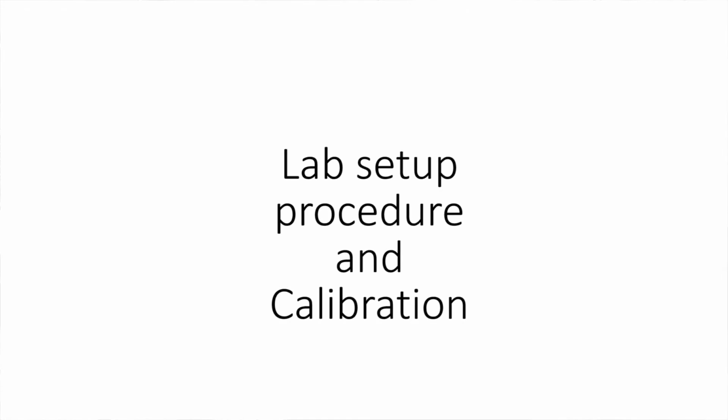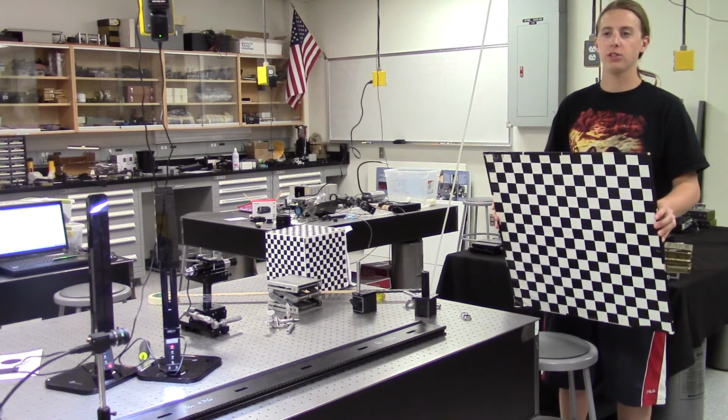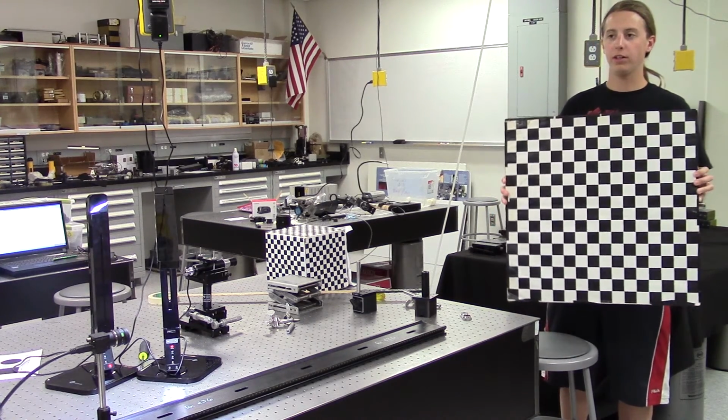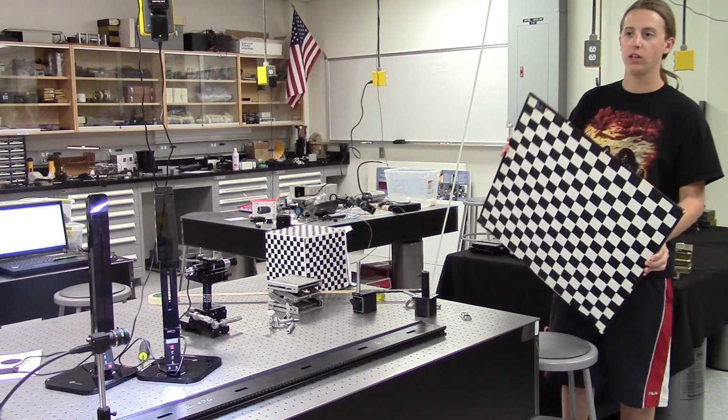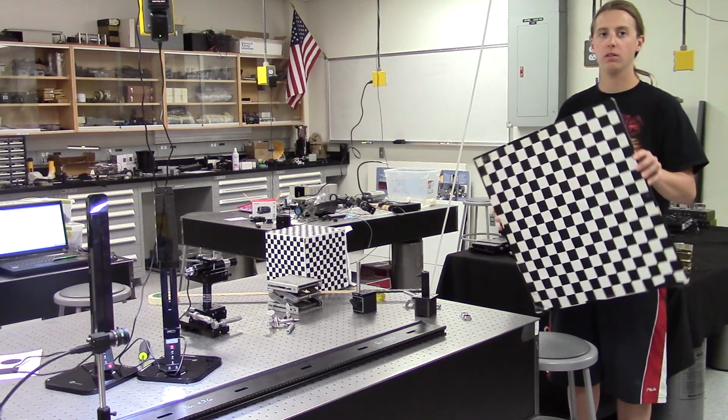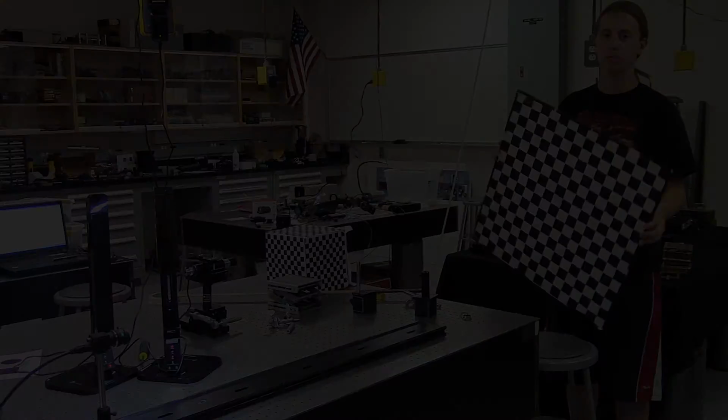We started our lab with the normal lens. After measuring the square's size, note we'll need this for calibration, we take the 20 images with the board in varying positions as Jacob is demonstrating. We'll then use these to calibrate the camera.